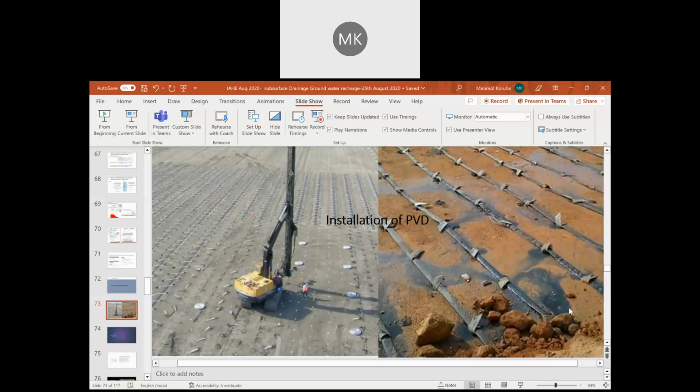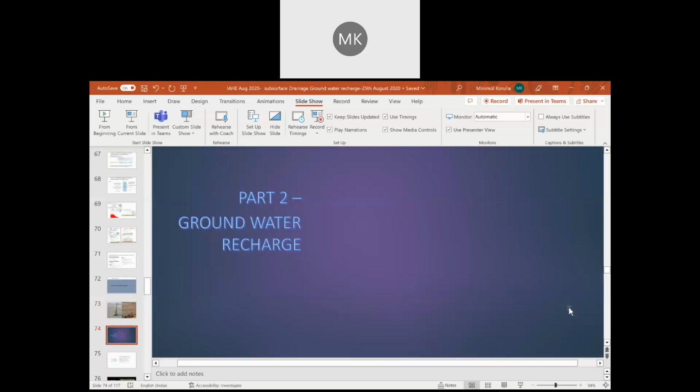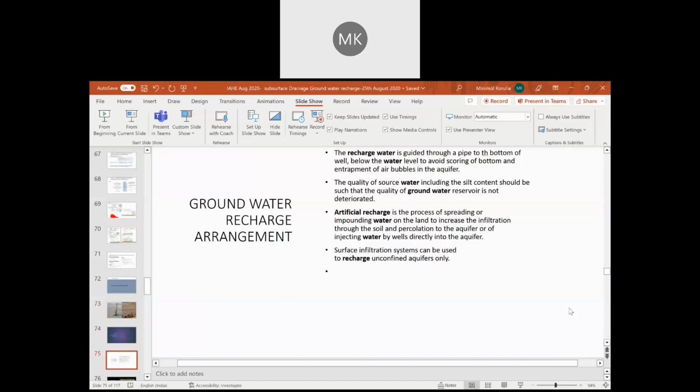So the geotextile should not be clogged, and for the design for clogging stability, anti-clogging stability, we require the same parameters: the apparent opening size, permittivity, and gradation of the soil. So the permittivity criteria and clogging resistance criteria will both be governed by the same type of calculations. The calculations use the apparent opening size, the permeability, and the soil type, D50, the average gradation of the soil particles.